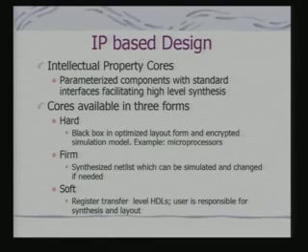The other variant of the core is called firm core, where you do not provide the design at the layout level, but provide it at the netlist level. That means at the level of connections between the constituent blocks, maybe gate level connections. So, what is the advantage? It can be simulated definitely, because you have a netlist connection and specification at the component level. It can also be resynthesized with necessary changes. So, the visibility of the design is more compared to that of a hard core.